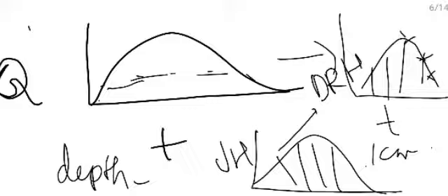Before multiplying the unit hydrograph with the depth, make sure we have subtracted the losses from this depth, because when we drew the unit hydrograph, we neglected those losses. So make sure that when we are multiplying, we go through the reverse process. Okay, multiply to get this.